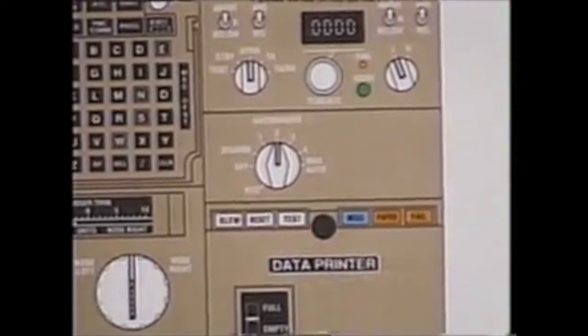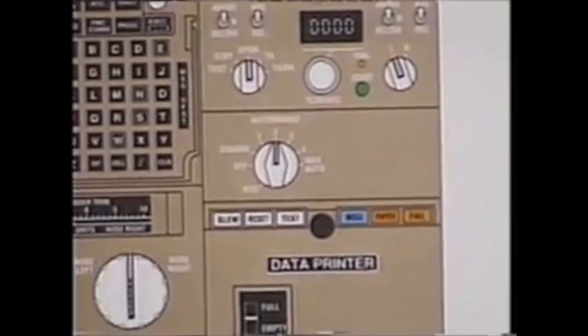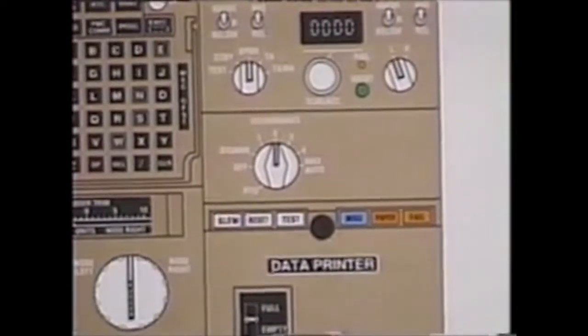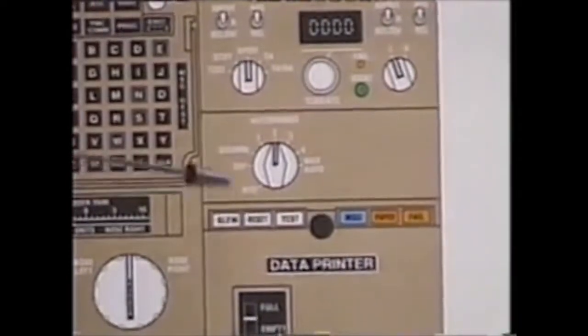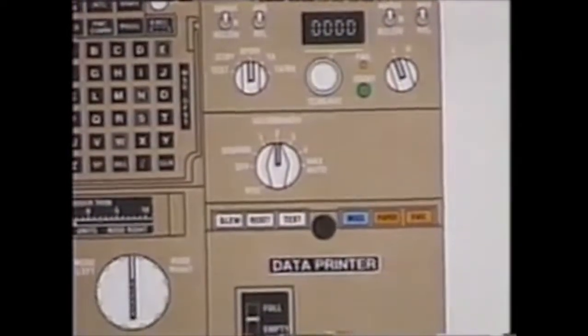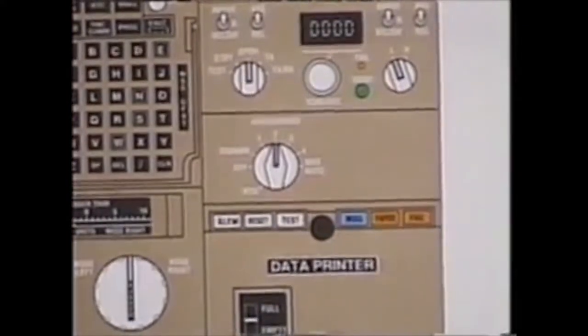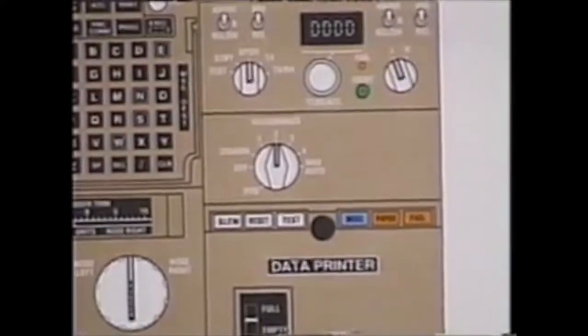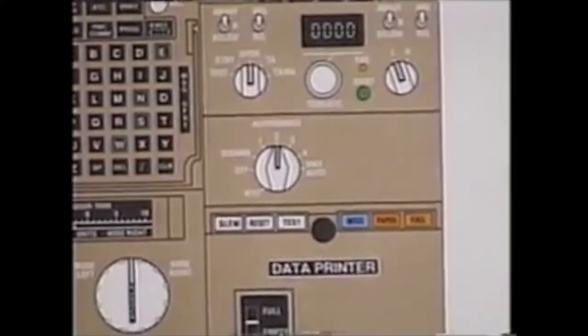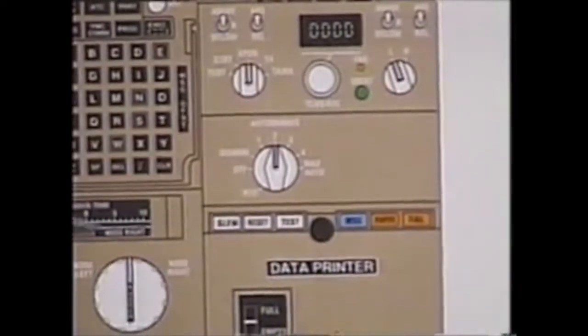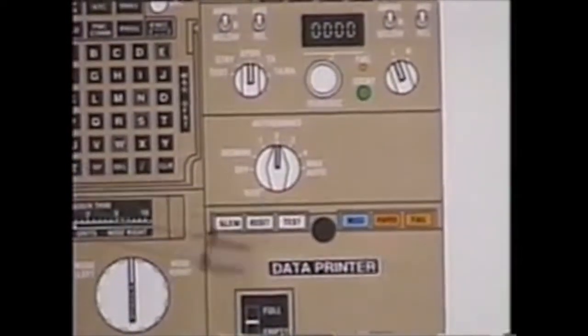If RTO is no longer desired and you wish to disarm it, the preferred method is to touch the brake pedals, or you could reach down and physically select it to off. If you touch the brake pedals, you do not have to outbrake its level. Keep in mind you cannot reselect RTO from the cockpit. The selector will stay in the RTO position.